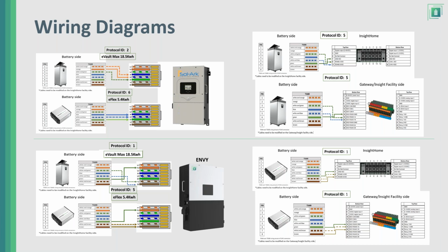All this information is available on our website. When you go into fortresspower.com, you go into the support section, and you will see inverter guides. In that inverter guide, you will see these configurations. So you have to make sure that the cable coming out of the master battery ends up in the inverter using those specified pins, which are color coded.